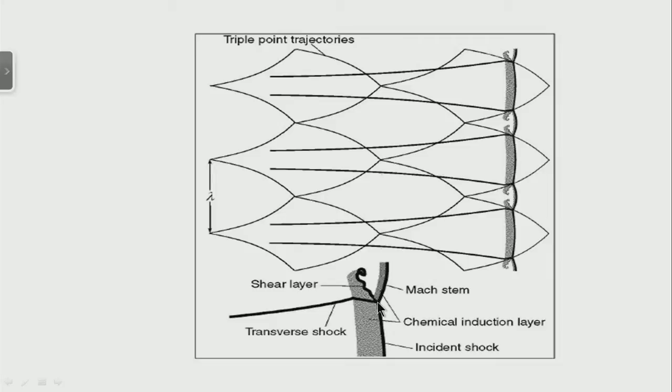I have vorticity at this particular intersection point, and therefore, when a detonation wave propagates, this particular point, the triple point, is capable of leaving a record. If I put a paper coated with some material like soot, or some substance which can easily be written upon, like a paper on which I put some carbon deposit and scratch on it, I can easily write on it.